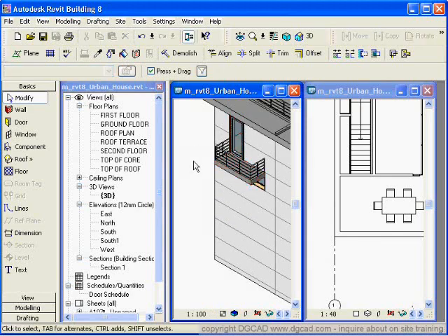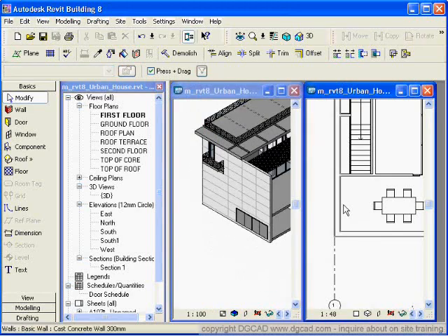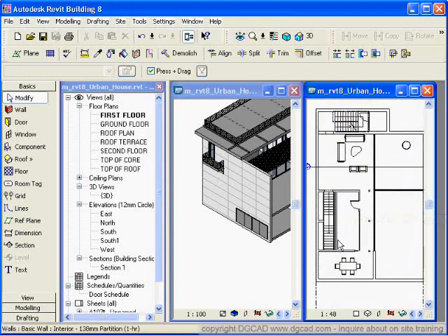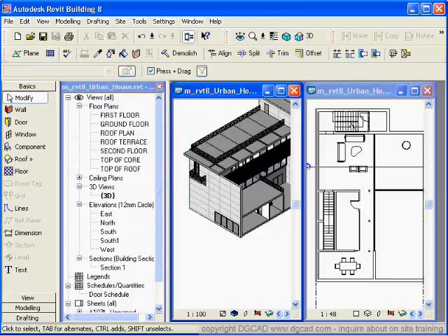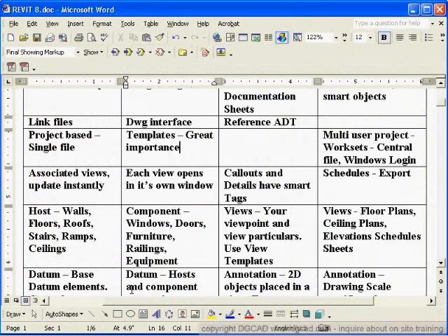And then we've got different objects, and I'm really just talking about the windows here and the fact that you do have different windows, and we have some shortcut keys. SD will give me a shaded view, and HL will switch that back. Similarly here, HL will give me just a hidden line view. SD gives me my shaded view. So we've got our different views inside of here, and they update accordingly. Let's go back into here and check our notes.